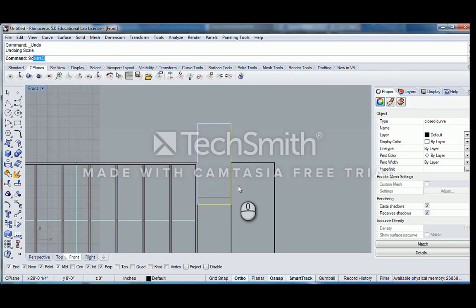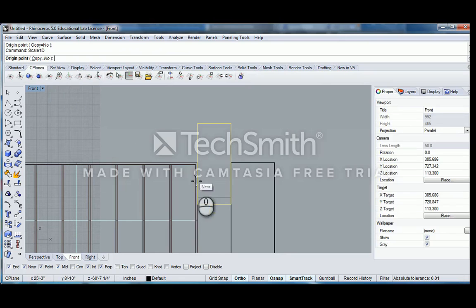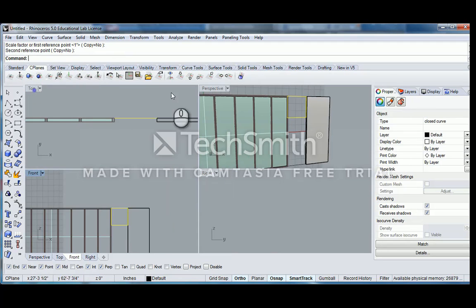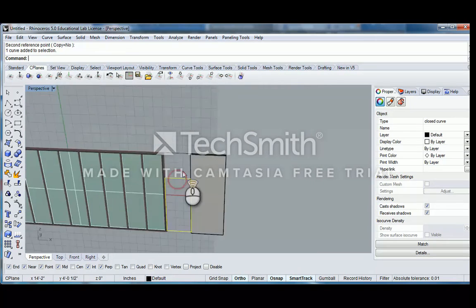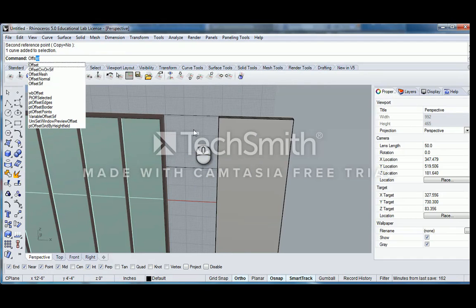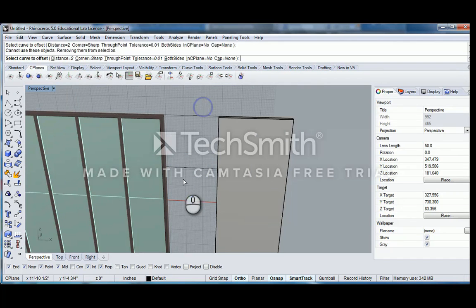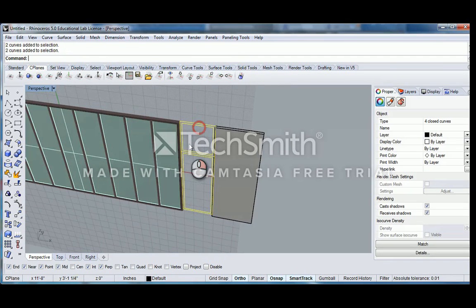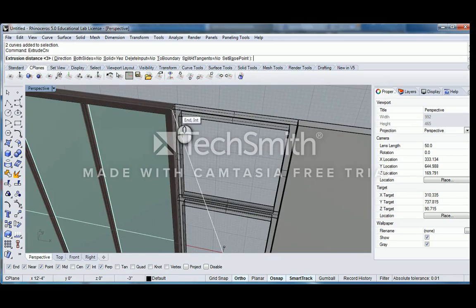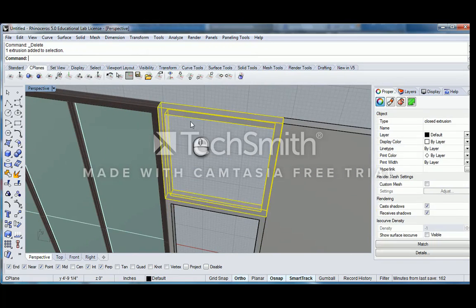Keep scaling that. The next thing I'm going to show you is aliases, because this is driving me crazy. So scale 1D this shape. Let's see if that actually worked. Let's see if what we were doing in 2D actually didn't distort in 3D. Looks like it was okay. So now, in theory, we could offset these lines and make a little transom. Extrude curve. I should have deleted input, but we'll just delete it there.